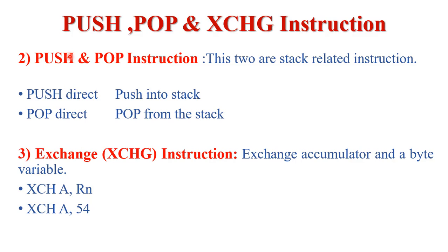Now, other data transfer instructions are the push instruction, pop instruction and exchange instruction. First we will learn what push and pop instructions are. Push and pop, these two are stack related instructions. Stack is basically a portion of RAM in the 8051 microcontroller where we store data temporarily. If we want to store data into the stack, that operation is called a push operation, and if we want to retrieve data from the stack, that operation is called a pop operation.